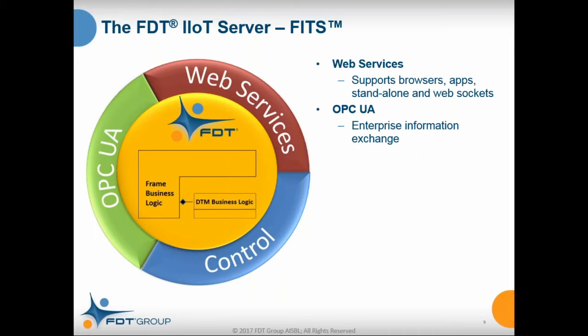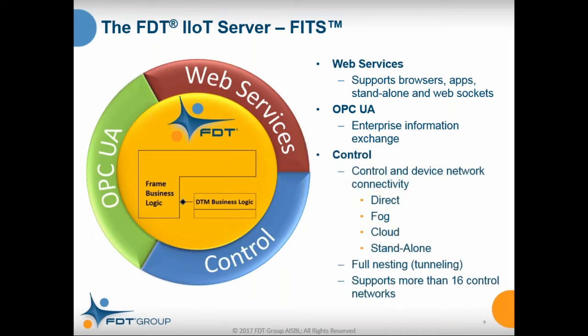You can also use OPC UA for some of the same things that you can use web services. So depending on where the customer's technology preferences are, you could write a custom client using OPC UA interfaces, or you could write that custom client using web services interfaces. And some customers will make that choice for us. Others will just say, as long as it works, I'm fine.